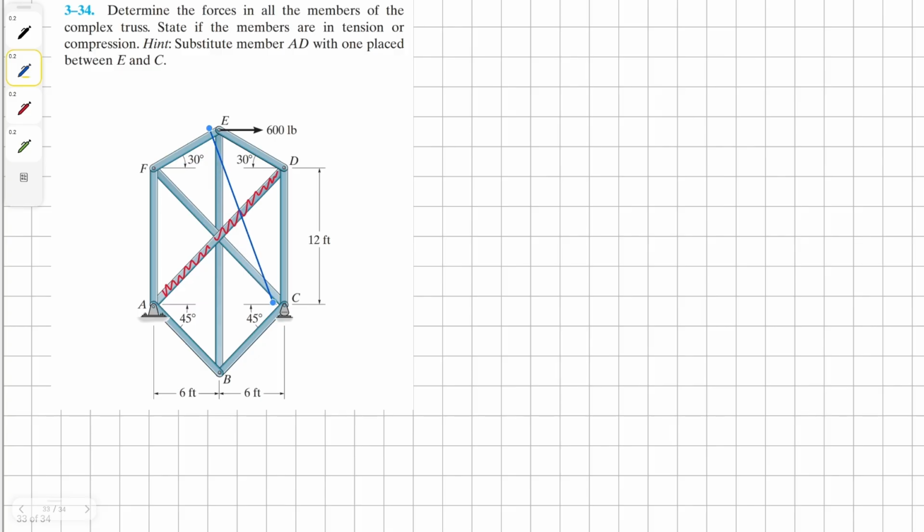We're going to name it angle theta. To find angle theta, we need to determine the total length of member EB along the total line all the way to the E. To do that, we just need to find our length between joint FD and the joint E. So it's going to be 10 times tan 30 down 6 feet, and it's going to give us the length of this portion of this member EB. So this comes up to be 3.46.